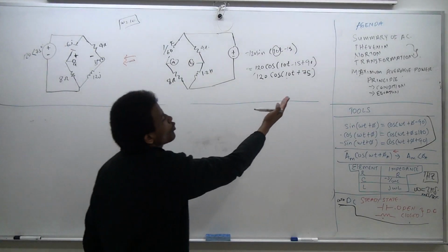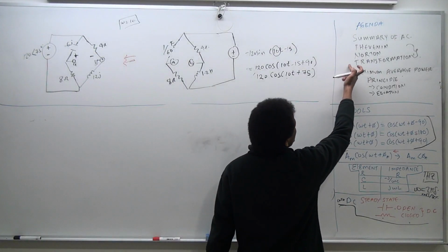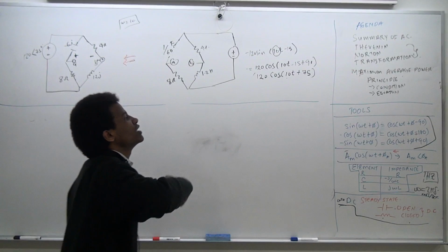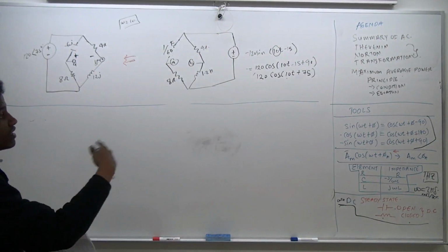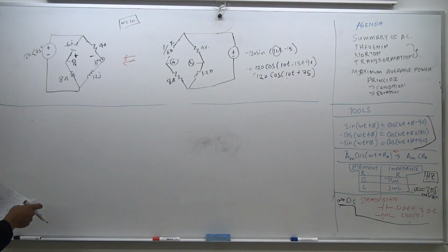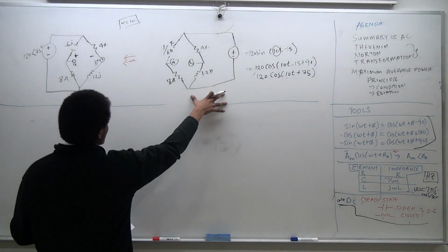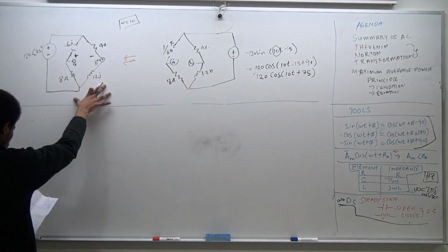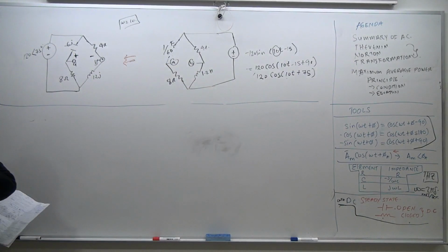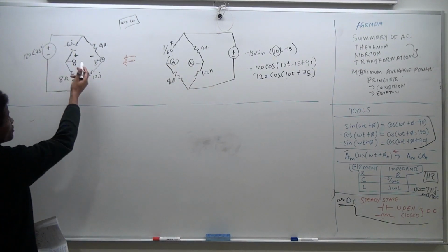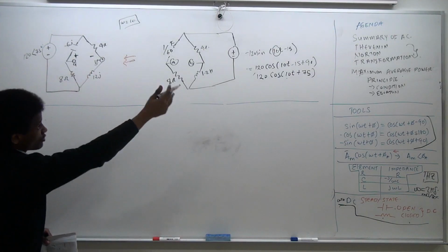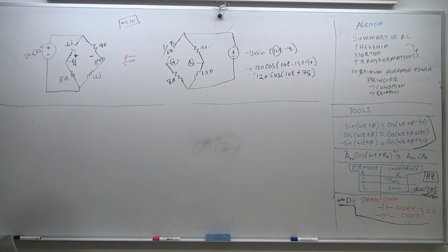If you're able to do even one iteration, you can apply it iteratively to a circuit, just like the way you did under DC. So the problem is given to us here. We've taken the problem from the time domain into the phasor domain, and now we're asked to find the Thevenin equivalency of the circuit as seen from terminals A and B. So how would we do this?